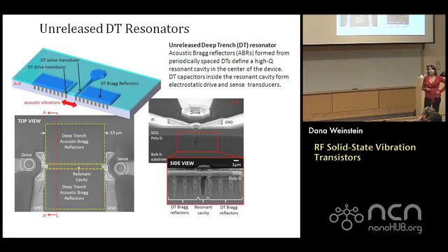we actually fabricated some of these types of structures at MIT. Now, not as high aspect ratio, of course, and not as beautiful as IBM's process, but still demonstrating the concept. What you see here are deep trench capacitors that have, in this case, a nitride conformal film to form the capacitor, and they're backfilled with polysilicon.